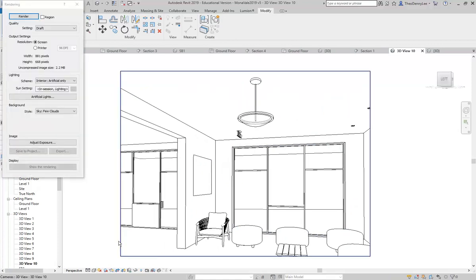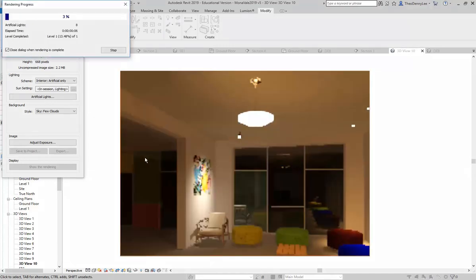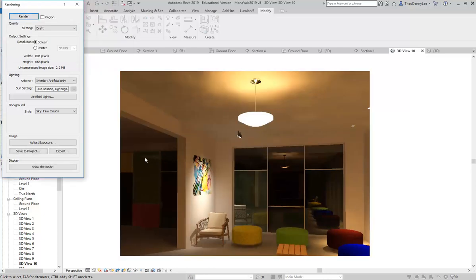And so, I'll just show you though, when you're working with pendants, even without getting into web, again the distribution is quite different to directional lights. So again, the best tip I can give you there is trial and error. Put them in and render them before you go too far. And again, I see so many people put a lot of lights in and then really struggle just to work with the basic settings, because when you put more lights, it takes much longer to render and you can't test things out as easily.